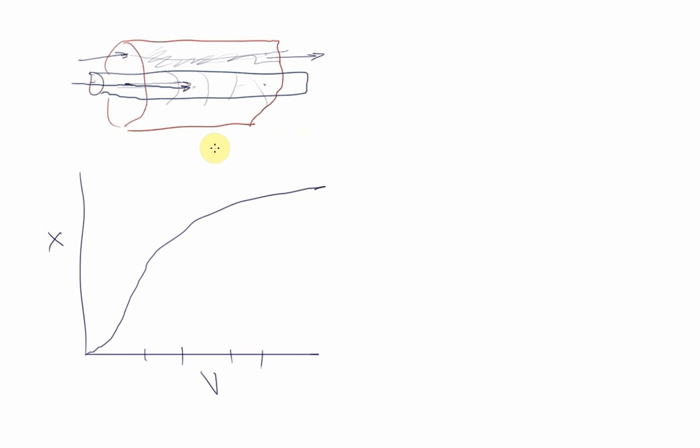So that's really the influence of concern to us here, that because the rate of change of conversion is dependent on reaction rate, and because we know reaction rate is a strong function of temperature, then the change of conversion down this tube is strongly dependent on how the temperature is changing through the tube. So although we've made some approximations, we've gone back and checked those, and we found that they were fairly good approximations, and we have to keep doing that. We don't want to rush into making approximations that might give us an incorrect temperature change.